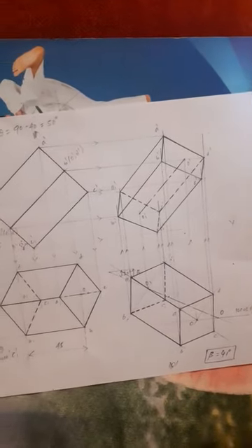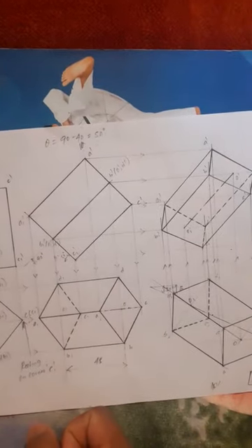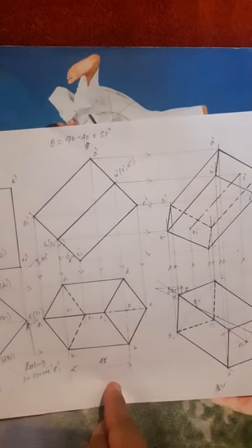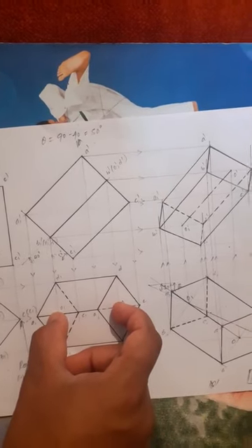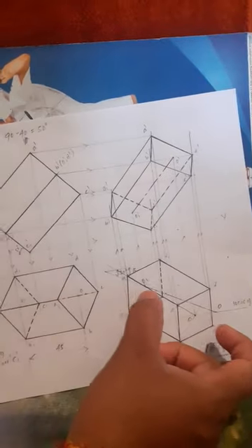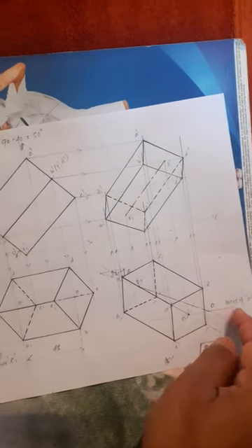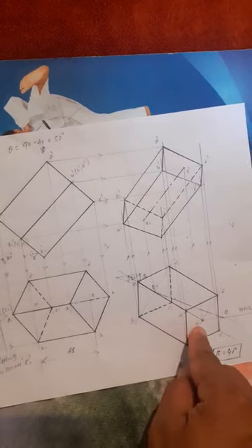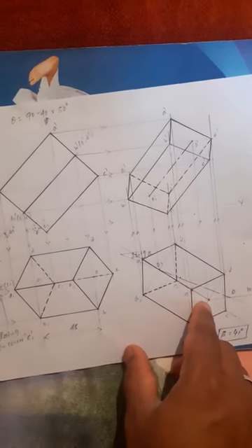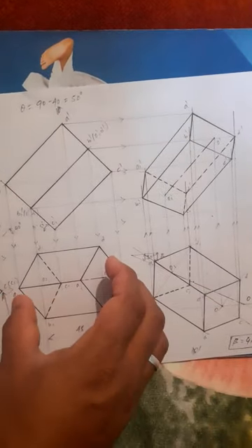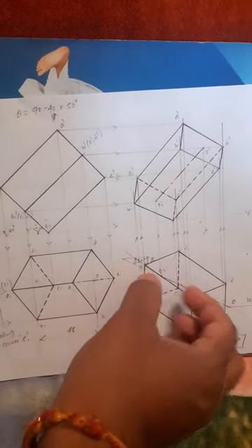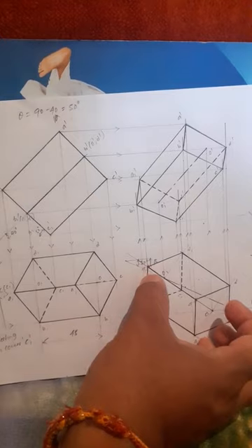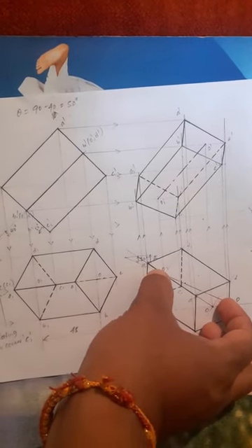What is the apparent length of the axis? You can see it in the second position top view, O1 O. It is less than 60 mm. Measure it through the compass. Then with O1 as center, draw an arc that cuts the locus of O. That will give the second position of O. Right? Now we place this solid on the O1 O, that is the beta degree line.